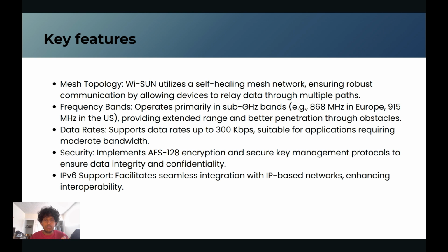And the WiSUN architecture also guarantees a decent data rate, that is 300 kbps for data transfer within applications. It has moderate bandwidth, and the creators have also included the AES 128 encryption key, which is a very strong encryption key to keep it confidential. And it also has IPv6 support in case we have to upgrade to the next IP level protocol as well. It also helps in connecting it with IP devices. This is developed in a very different architecture than the IP protocol, so they have integrations to make it work with IPv6.